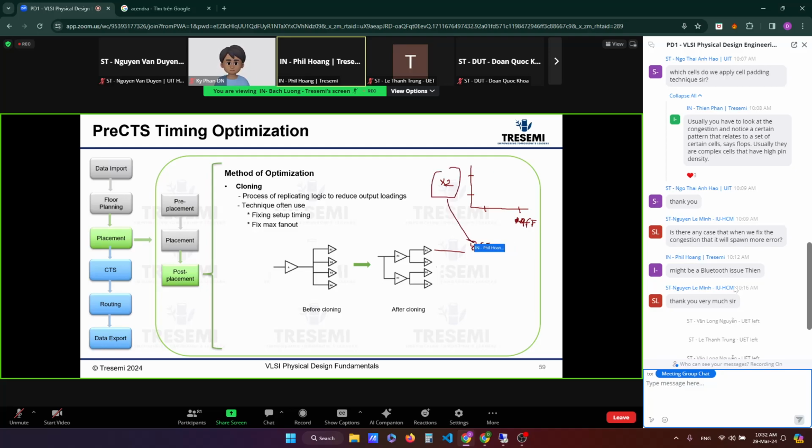Then you extrapolate. So you swap this one to X4, and in the table X4's max cap can be, like, 10 femtofarad. So if X4 is 10 and you're driving 8, then you use X4. You're not extrapolating when you drive an 8. That's how it relates to characterization in terms of the table. I hope that additional explanation will help you figure out how buffers can do that.